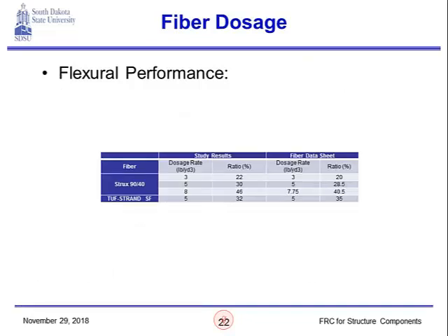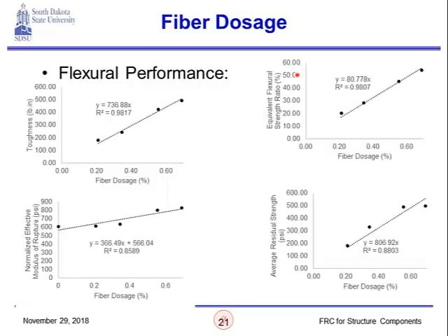One of our objectives here was also to try as much as possible to compare our values with the manufacturer's claims, and they actually matched pretty well. We didn't have manufacturer claims for all the fibers, but for these two specific synthetic fibers, we had some manufacturer claims in the fiber data sheet. And that was, if we go back here, for the equivalent flexural strength ratio.